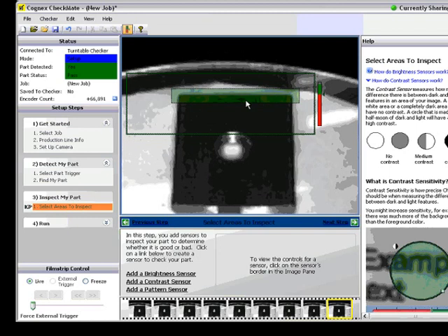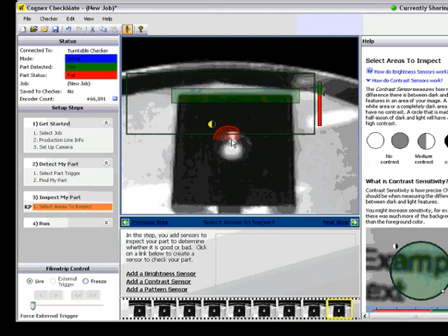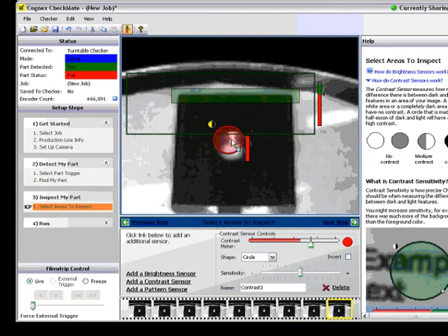They're round. So, do an inspection here. I'm going to grab a contrast sensor. You simply highlight the tool, click on the tool, and you get a yellow box again. And then you can move that up to the screen, and you see how you have a light and dark region next to my mouse pointer. That tells me that I have a contrast tool selected. Or point the arrow on an object, and it throws down a tool for me.